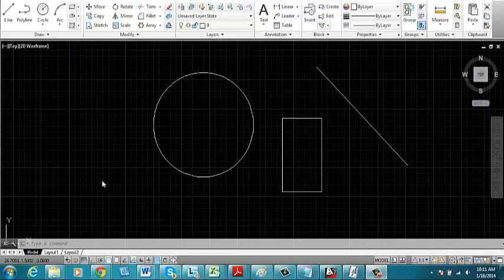In this video, I'm going to introduce you to AutoCAD's object snaps. Object snaps are a means in which you can be a more precise draftsman. They allow you to snap to certain positions on the screen based on objects that are existing. The icon to turn on and off object snap is along the status bar here on the bottom. On my screen, it is 1, 2, 3, 4, 5, 6 icons over. And I'll show you a little bit about how this works.